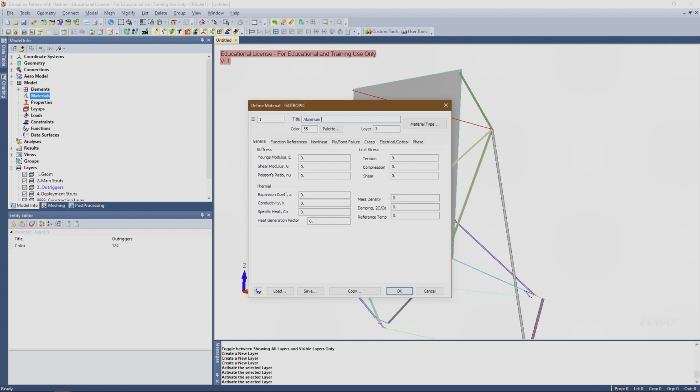And for rigorous aerospace analysis, you would specify, if we're going to call this 2024, obviously there are different alloys of aluminum that have different strengths, but also, to go a level deeper, even the way you form the same type of alloy can give you slightly different strength properties.